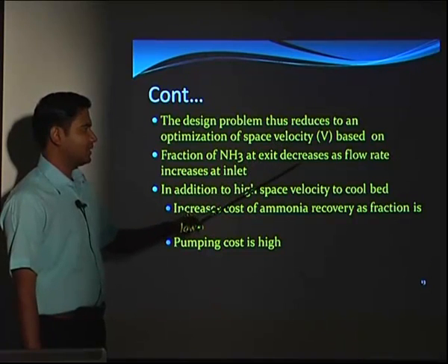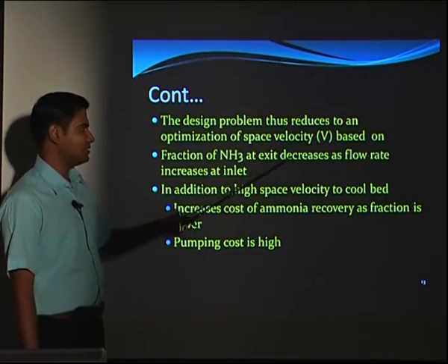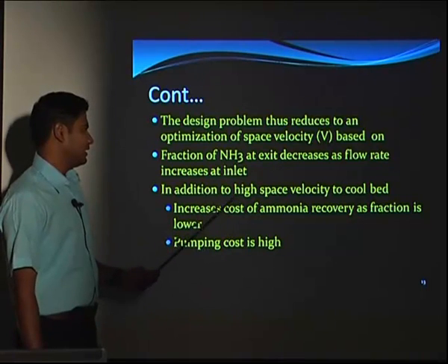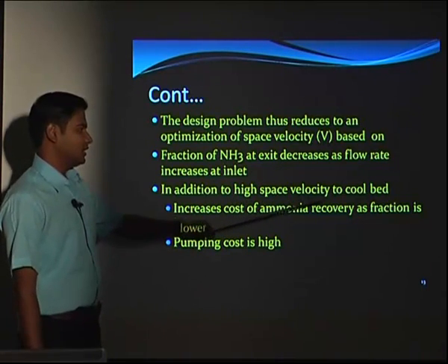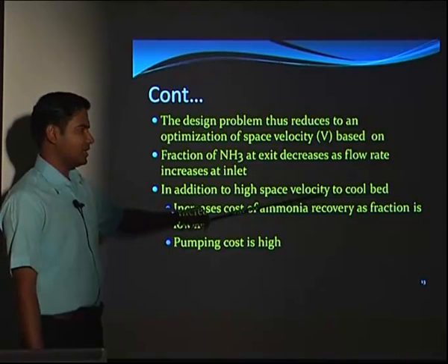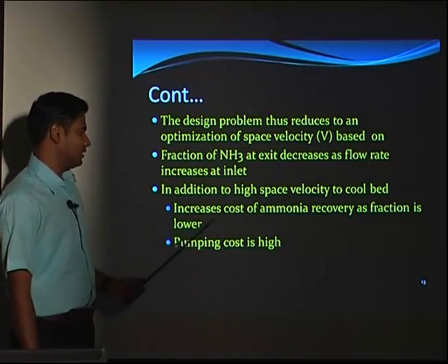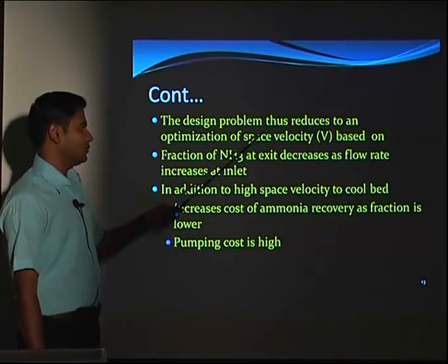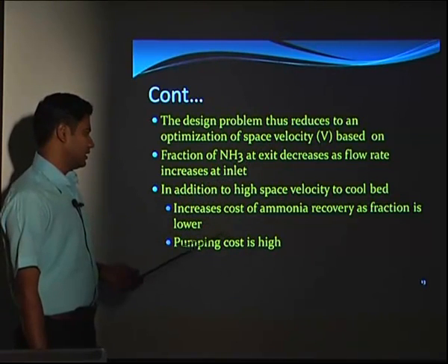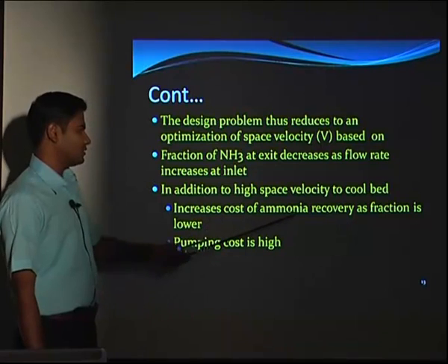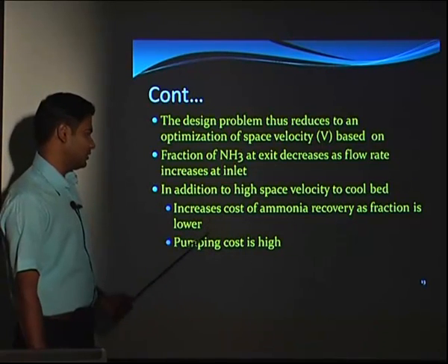So the more the space velocity, the more it will decrease. So again, it's the problem. Then in addition to high space velocity, to cool the bed which is at high temperature, in order to achieve a low temperature of the bed, what we can do is pass more airflow to cool the bed. But this increases the cost of ammonia recovery as the fraction is lower.